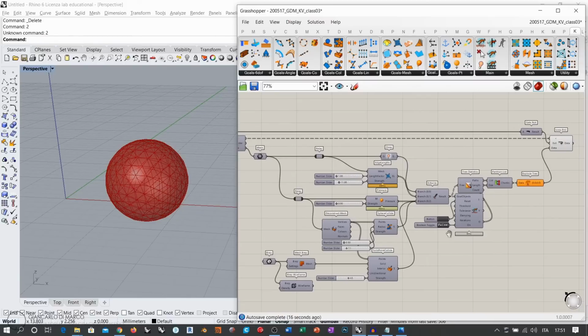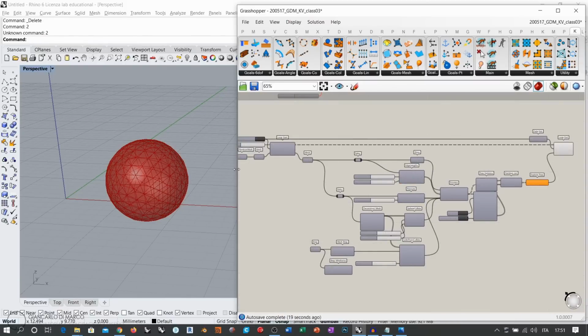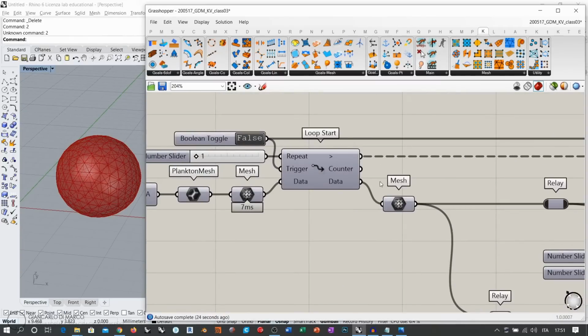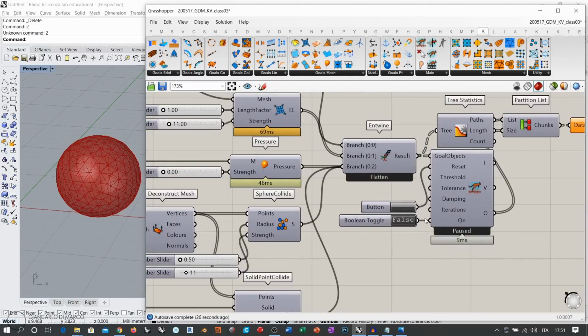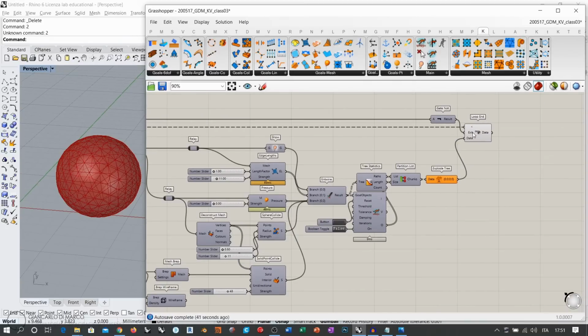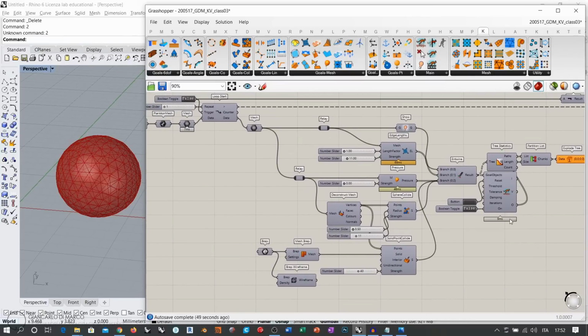Okay, problem in this case is that I have two toggles. One toggle is firing the loop, and there is another one that simply makes the simulation run. So I need these two to be connected, and therefore when this is true, which triggered the loop, it becomes false, so makes the loop stay inside the loop. And I want, when this is true, I want this to be true, so Kangaroo can also run the simulation.